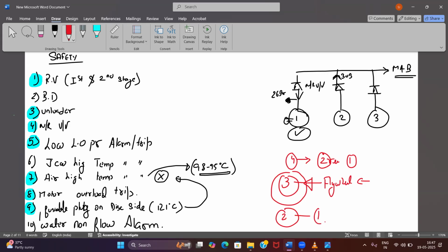Now in your two stroke, every cycle I have one power stroke. So comparatively, which flywheel will I need bigger? What is the function of the flywheel? It will supply power when the power stroke is not there, right? To turn your crankshaft, isn't it? So that it can smoothen the rotation of your crankshaft, isn't it? Otherwise, it will become jerky, right?